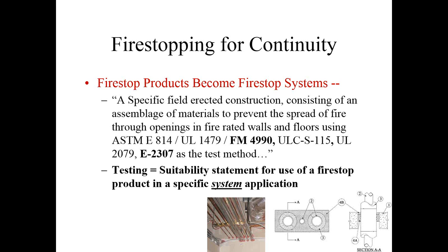The difference between ULC S115 and UL 1479 is the pressure in the furnace for the plastic pipe. And the hose stream test is optional in some cases.